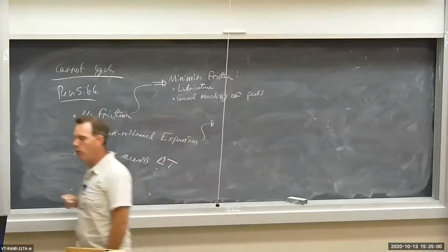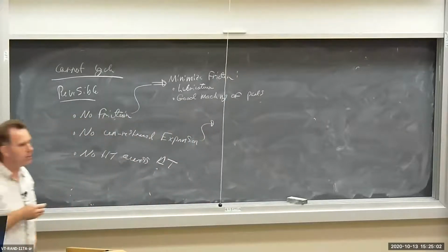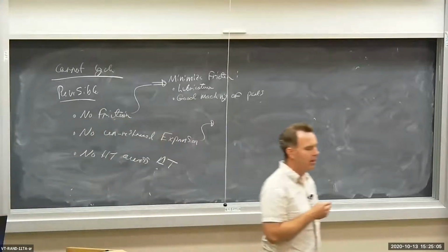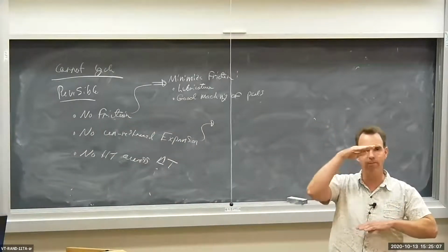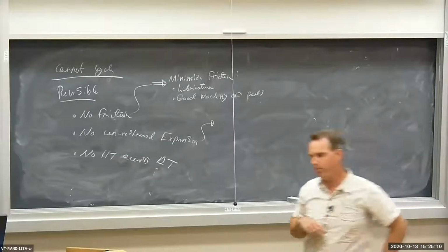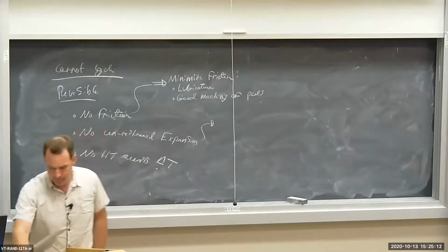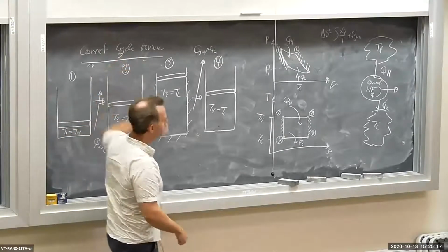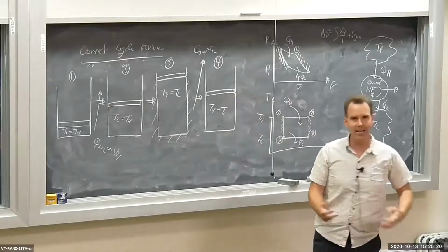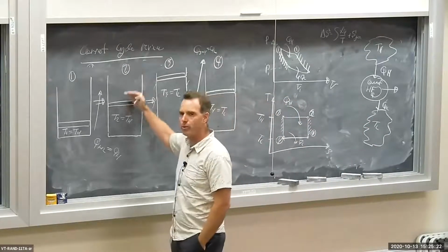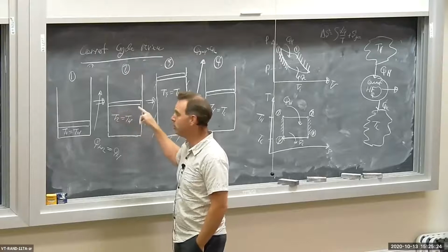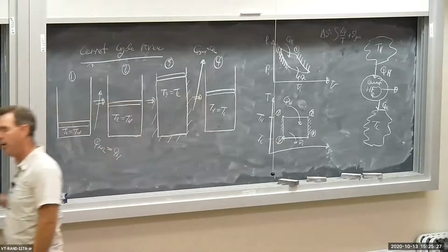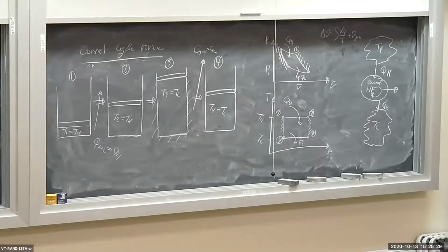Well, we can approach or minimize the presence of unrestrained expansion by having the piston cylinder device work very slowly. Remember, unrestrained expansion is caused by the piston jerking up and down so quickly that the gas doesn't have a chance to move along with the piston, forming a low pressure or perhaps a partial vacuum near the piston. Remember, unrestrained expansion is irreversible, so we want the piston to move slowly.